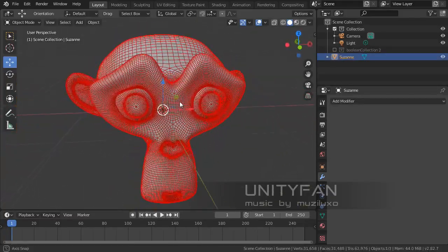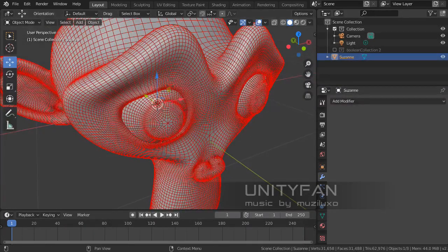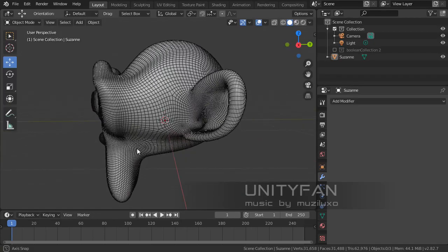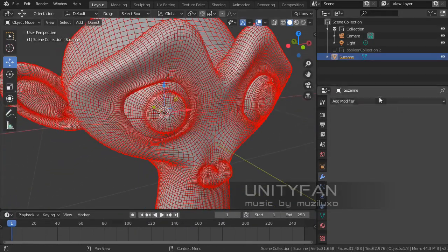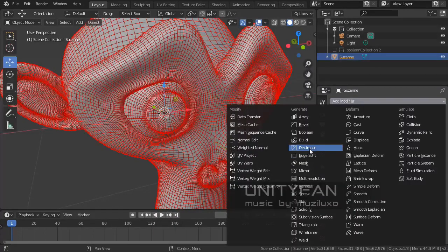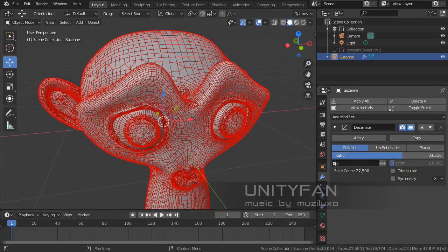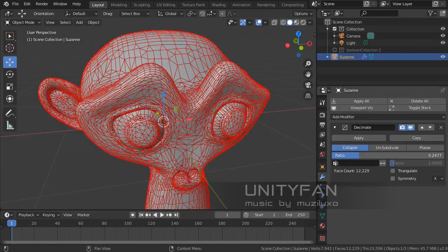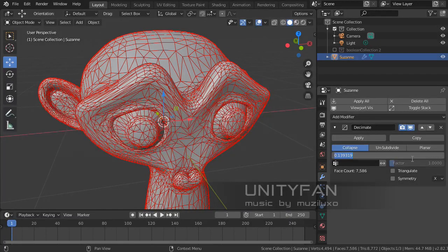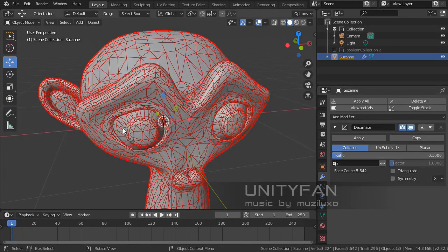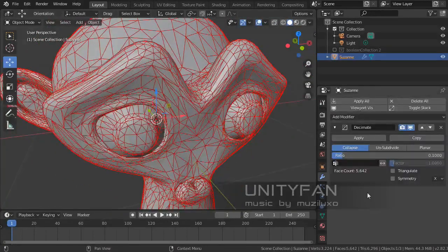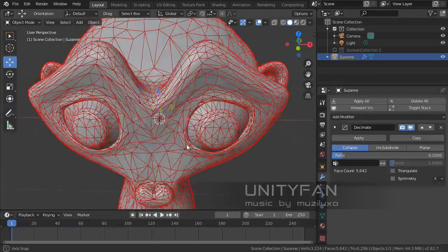and we need to optimize the scene, and right now it's 31,000 faces and 63,000 triangles just on the one geometry piece. And by using this decimate modifier, we can optimize it. We can type just 0.1, and now there are 5,000 faces and 6,300 triangles.